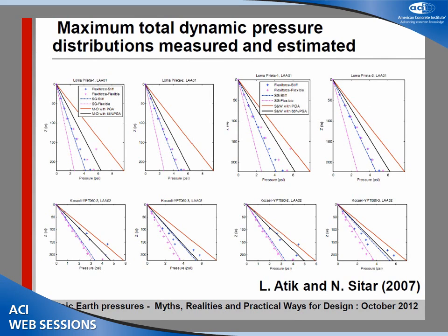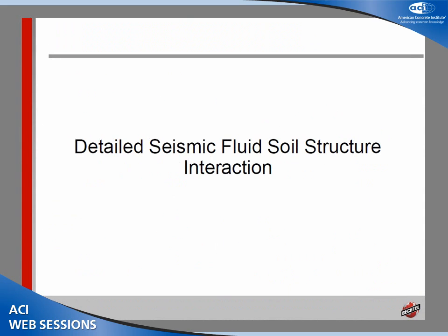And in terms of pressure distributions, again the same situation. Normally Mononobe-Okabe was enveloping, so pretty much if we design using Mononobe-Okabe it is already conservative. If we use now the elastic pressure distributions from Wood, it will be even more conservative. But anyway, now I will show you what we do for nuclear, which is even more conservative.